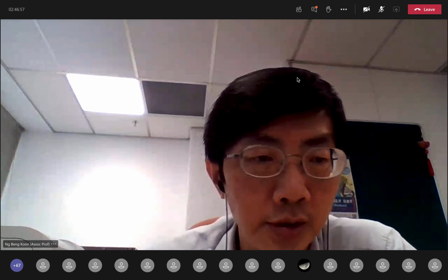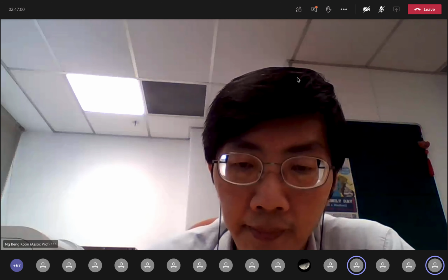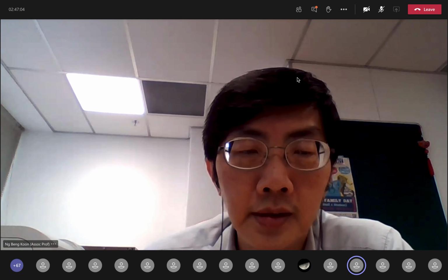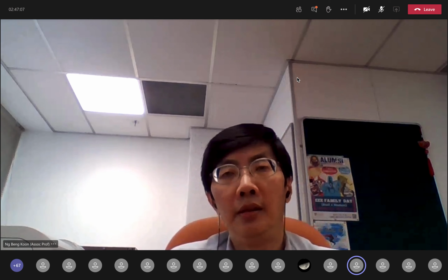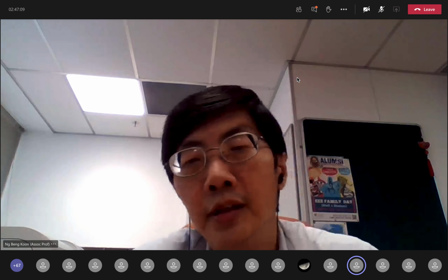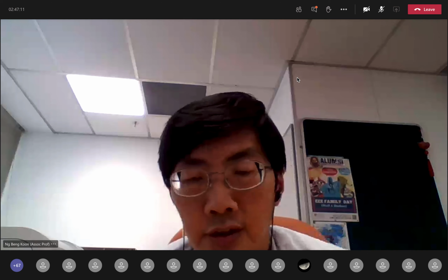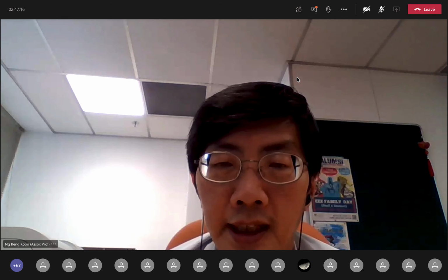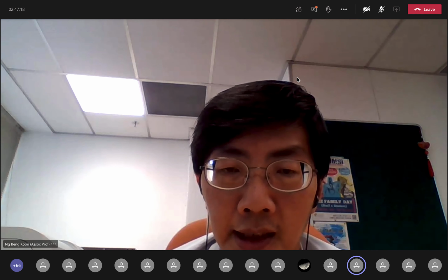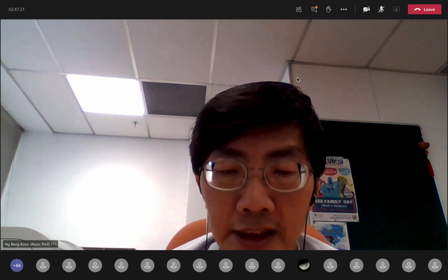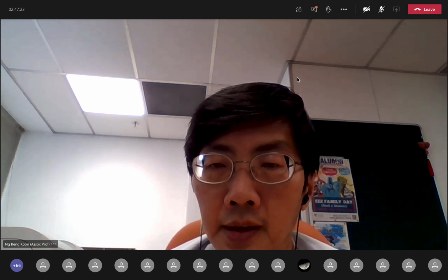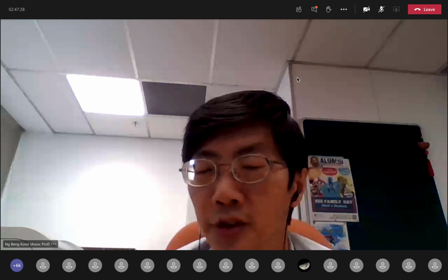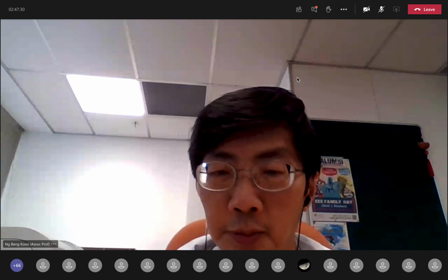Okay, any other last question before we end the session? Prof. Yep. Just now when you were talking about the impurity saturation, it got a bit too quick and I didn't catch. Okay. Yeah, the impurity saturation basically refers to the case where all the dopants are ionized. Then that corresponds to the impurity saturation condition. Okay, because the ionization is saturated already. You can't ionize anymore because all of them have been ionized.